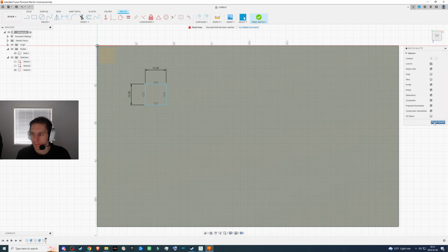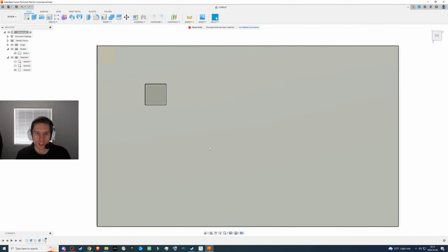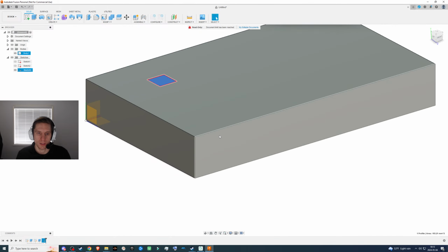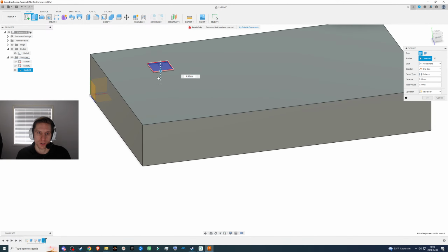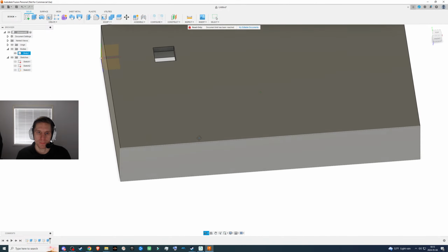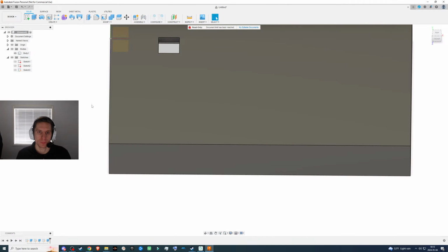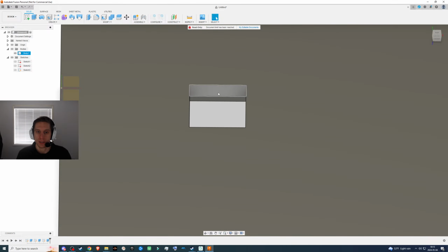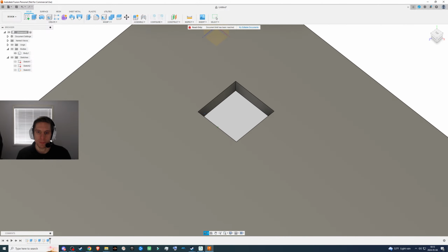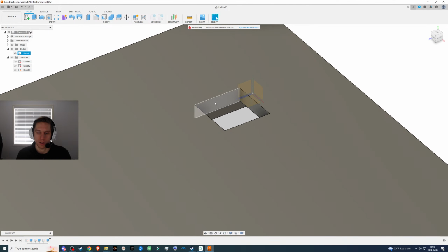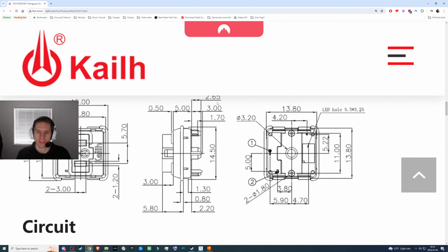So what are we going to do here? We can finish sketch, and you guessed it, we're going to extrude some more. So if we extrude, bam. Look at that. We've made a hole for our keycap. Now, here's an interesting detail. The horizontal part of a keycap is a little different.